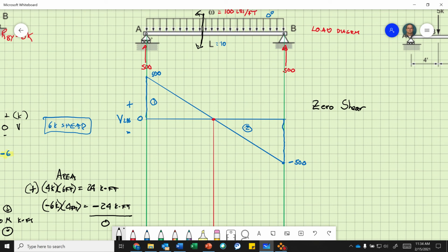And then make X here and X is there. X is that distance. That's what I'm looking for. I'm looking for this distance X right here. So if I cut the beam at some distance X and figure out what distance X the value of shear equals 0, I set up an equation and solve it.